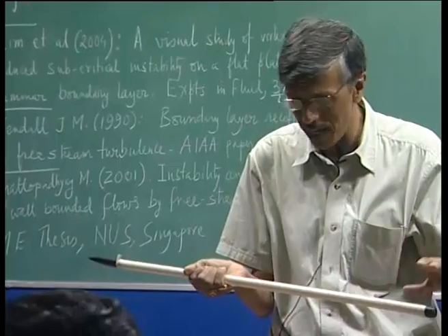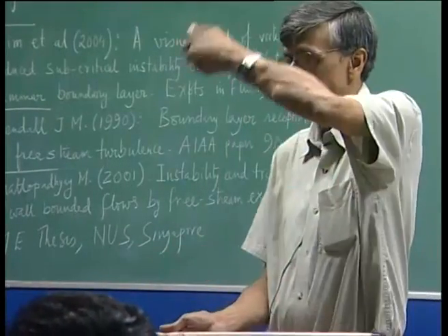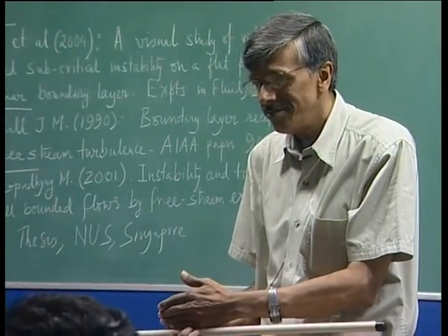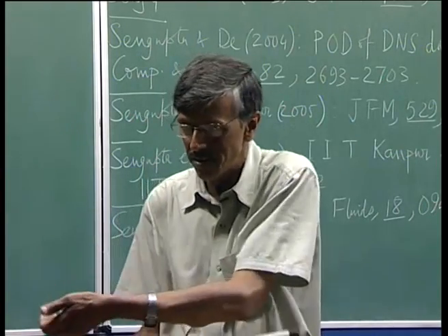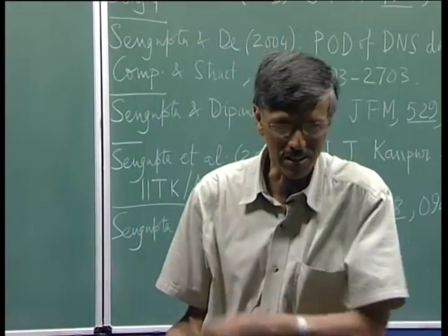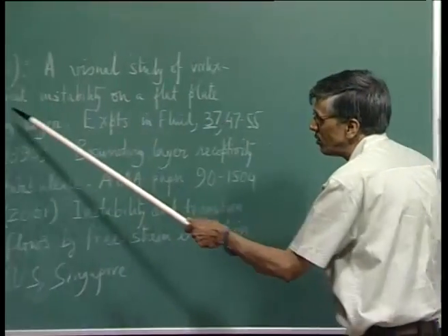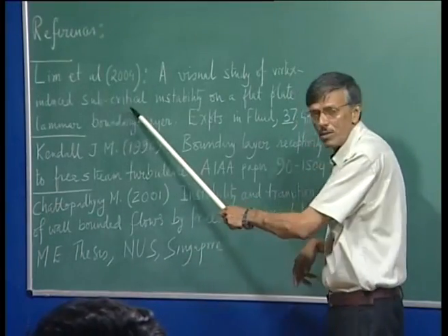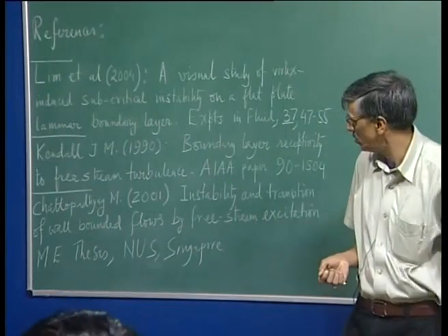One is one layer that remains parallel, very much embedded, and the other one has been lifted up on its own plane. So, it is basically a two-dimensional phenomenon, and this is due to this induced effect. So, that is why we called it a vortex induced instability, and because it is very much dependent on the large excitation, this must be a subcritical case. Okay.